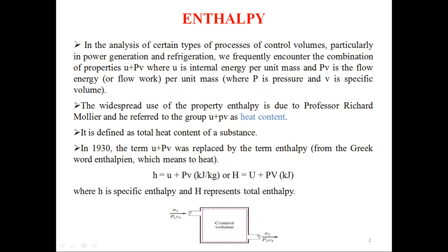In the analysis of certain types of processes of control volumes, particularly in power generation and refrigeration, we frequently encounter the combination of properties u plus Pv, where small u is the internal energy per unit mass and Pv is the flow energy or flow work per unit mass, where P is pressure and small v is the specific volume.